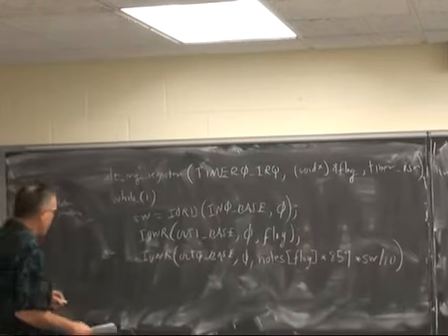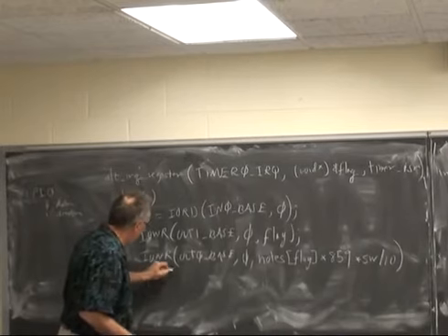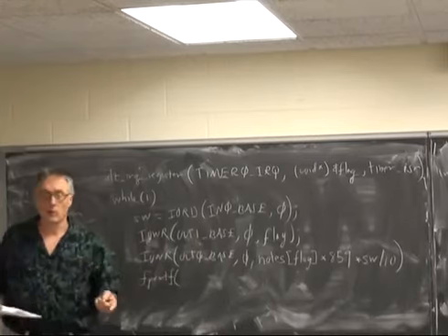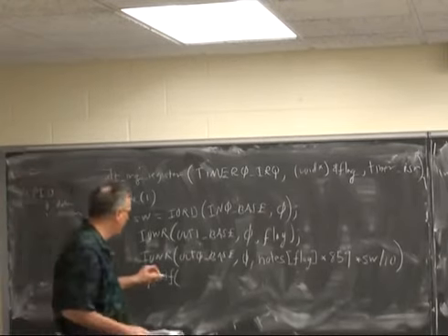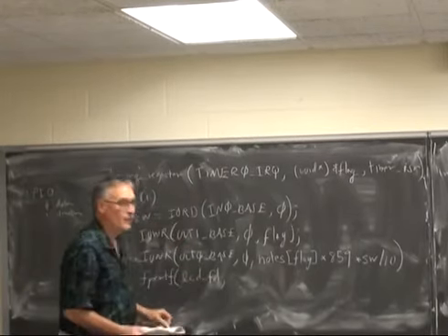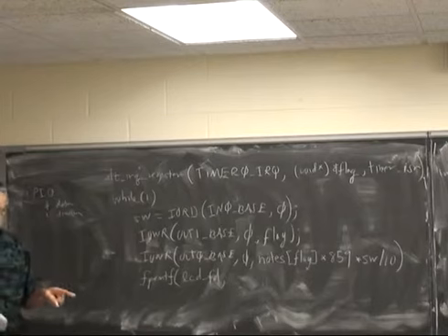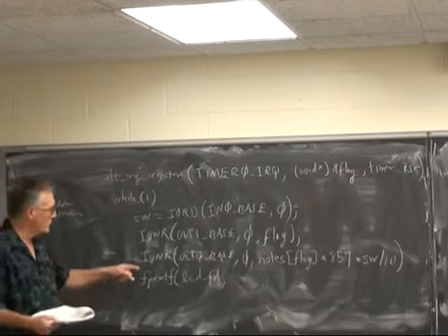So the last thing we have to do then is the easy part, which is an fprintf. You remember we opened an IO unit. We opened a file called LCD_FD. LCD_FD. That's a file descriptor. In this case, it routes the character stream from the printf to the LCD.